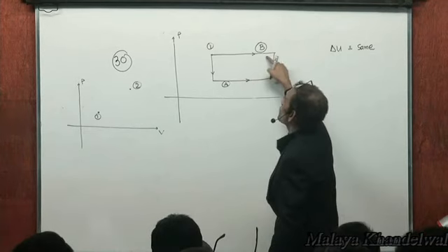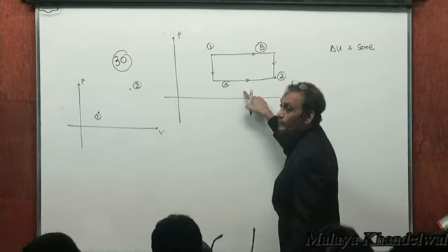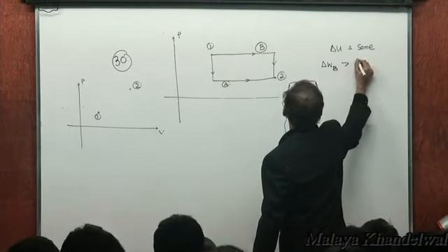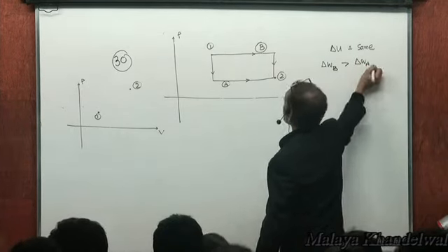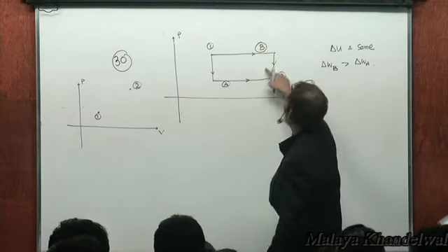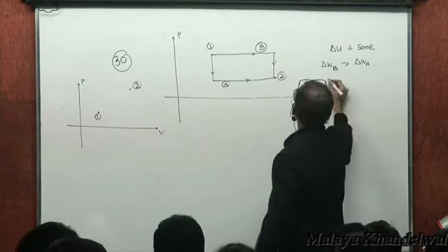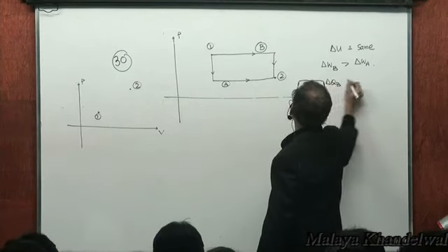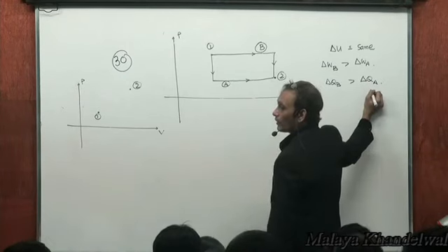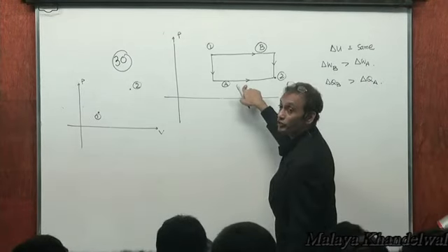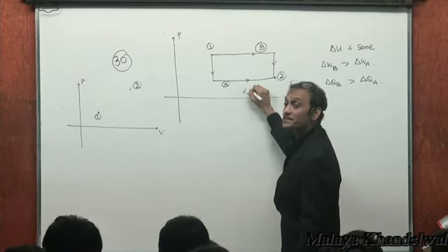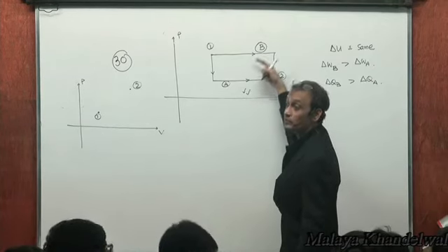In which case is the work done more, B or A? B. Work done in B is more than work done in A. Therefore, the heat supplied in B must be more than heat supplied in A. Therefore, A should be preferred in this case, because A requires less heat than B.